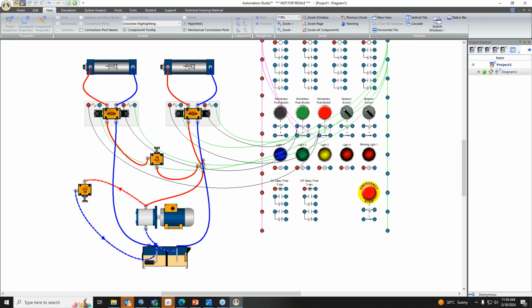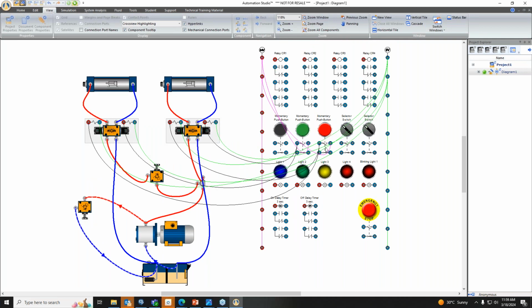And once the extension is completed, with the help of the pressure relief valve, the pressure will go into the other DCV and then this cylinder. So this was the operation of the pressure sequence valve that we have used in this circuit. You can see now it is working the same way. So now our hydraulic virtual trainer kit template is ready.